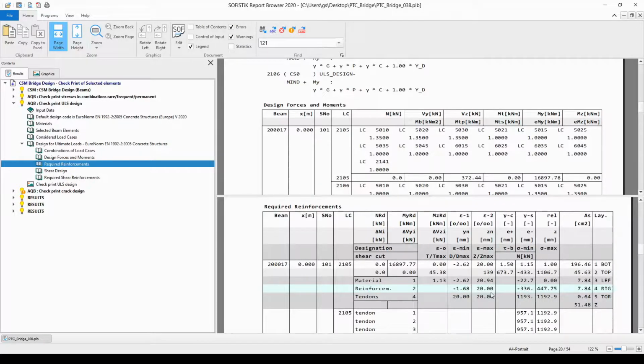Also, it is reasonable if we have 20 promille strain in the bottom reinforcement layer, then in the bottommost fiber in the concrete we are going to have a little bit bigger strain, since there is roughly 5 cm between the reinforcement and the bottommost fiber.